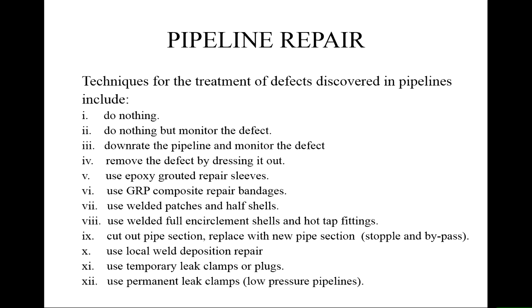Shells and hot tap fittings. Hot tap fittings means that they are connected onto the pipe during the pipe operation, so we don't need to stop. Cut out pipe sections and replace them with, as I anticipated there, bypasses, or so-called stopples.